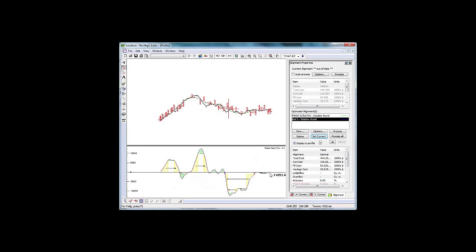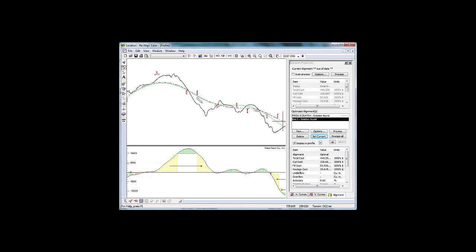And it's back to balance again. Now, right here, there's a bunch of fill, and if I put a bridge in there, and our software would allow me to do that, the optimizer will not, in general, zero the mass haul at that point. We don't have blocks or obstructions in the code as yet, so that's something that you'd have to manually deal with after the fact.